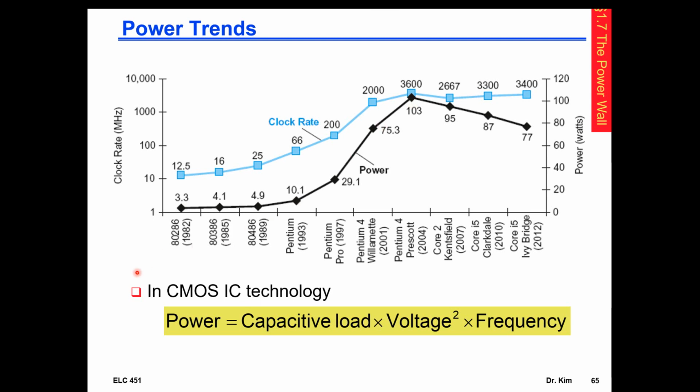And since we're talking about silicon CMOS technology, which is the inexpensive material, we cannot get that power supply much lower than 0.9 because we do have the physics of the material, the quantum work function of silicon, which says that transistors need about 0.6 to 0.7 to turn on. So you have to have just a little bit above that 0.7 volts. With some margin for noise, that's where we land at 0.9.